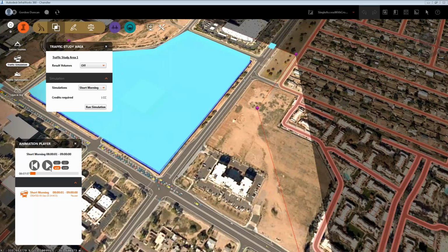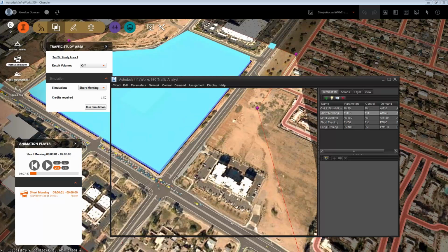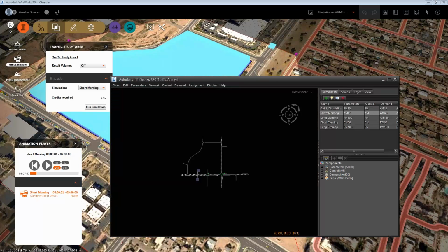Okay. Next question is, can you model traffic control, such as closing down a lane for construction? Yes, you can. So if you go into the traffic analysis panel, there is what's called lane restriction. So you can create some sort of restriction on the lane for like temporary closure or even vehicle type specific. So you could say, this lane is only available for construction traffic, or this lane is only available for transit vehicles or something like that.